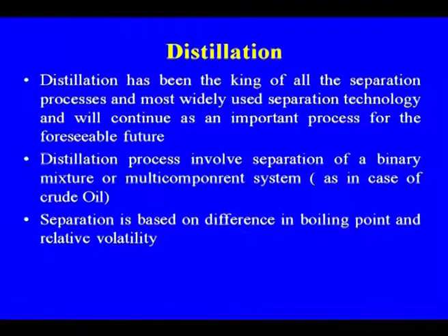The distillation process involves the separation of a binary mixture or a multi-component mixture, as in the case of crude oil. Separation is based on the difference in the boiling point and the relative volatility. Sometimes there is a problem when close boiling points are there, but there are still some developments in the distillation process, that is the azeotropic and extractive distillation, so we can also process the close boiling